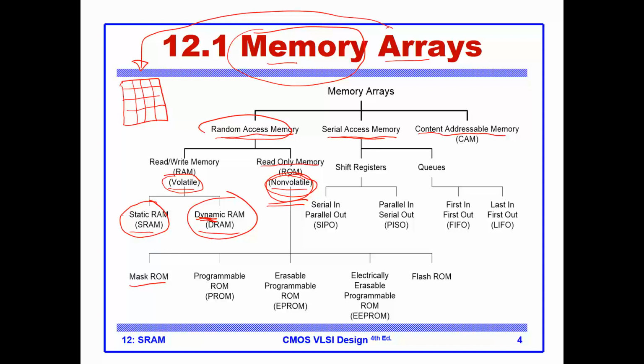They are more like implementing a truth table, to be honest, and that was the early application of it. Then we moved to programmable ROM, where you can fuse those transistors that you need or you don't need, to implement the truth tables or to implement the memory. This programming happens once and you cannot erase it.